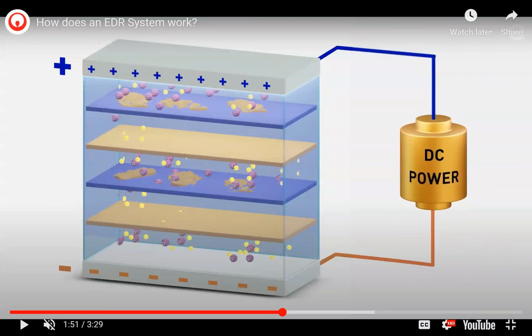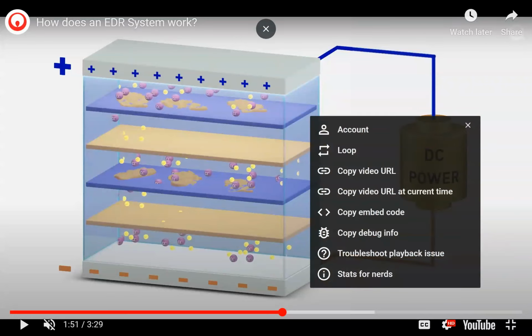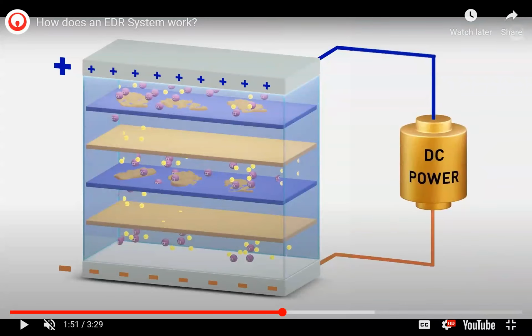If it's an anion exchange membrane, that means positive charge is fixed in the membrane, so negative ions will pass through by these three mechanisms which I explained in the slide. The negatively charged ions pass through the ion exchange membrane, but the positive charge will be repelled and won't be allowed to pass through.